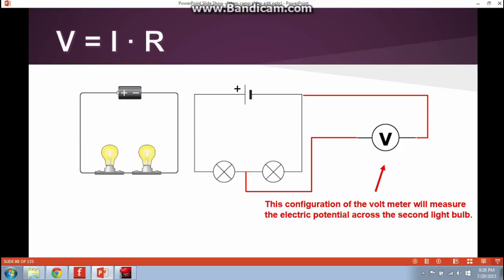But this goes to show that when you want to measure the voltage at a certain point on a circuit, especially a basic series circuit like this, you probe the area that you want to see, the potential of the drop that you want to see across whatever load there is, and then you put your other probe to ground.